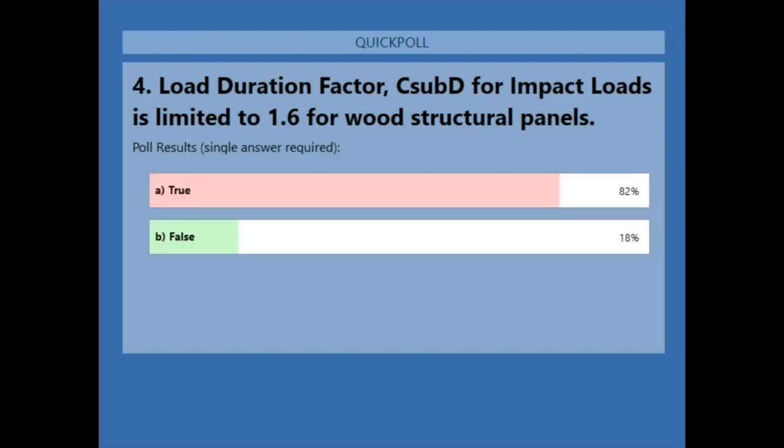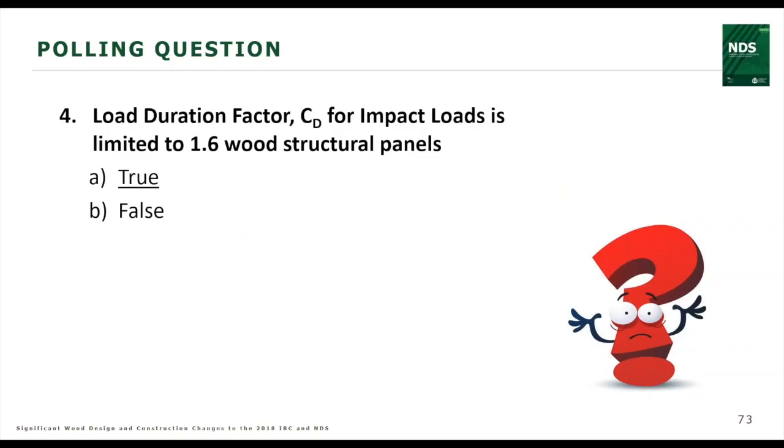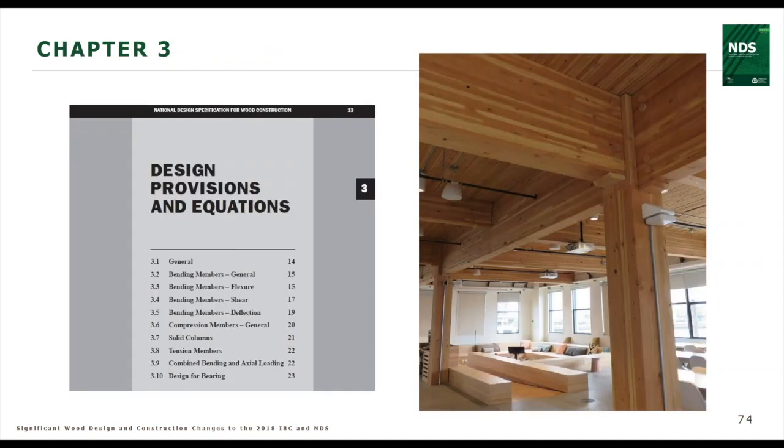And 82% say true, 18% say false. And what do you say, Lori? It is true. So that's that revision to this footnote of Table 2.3.2. So load duration factor for wood structural panels is limited to 1.6. So good for those of you who got it correct.